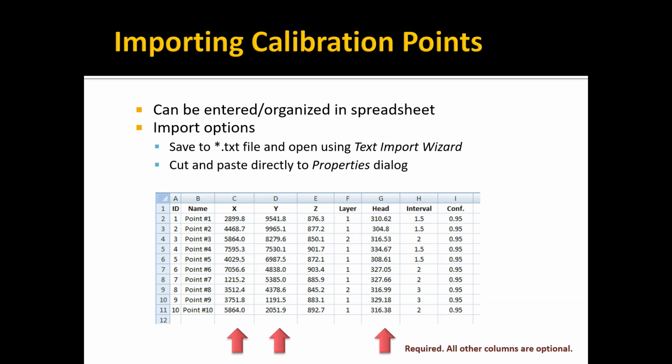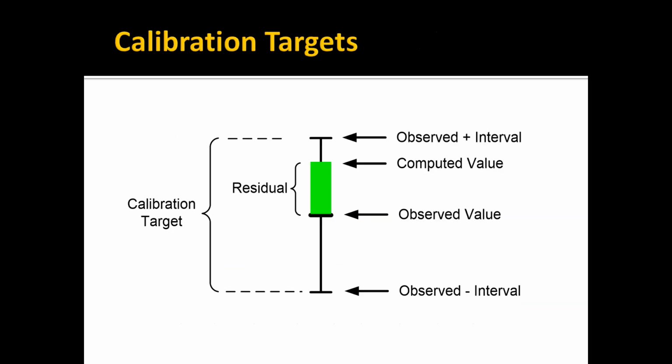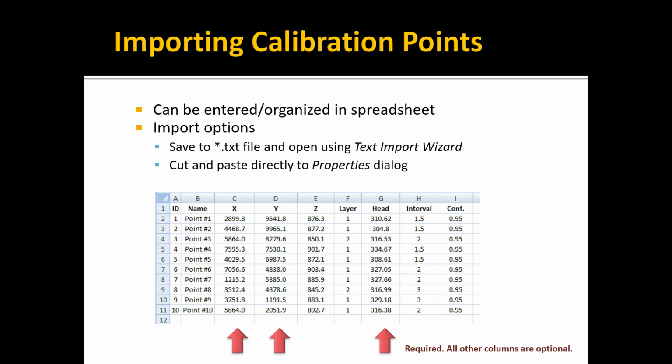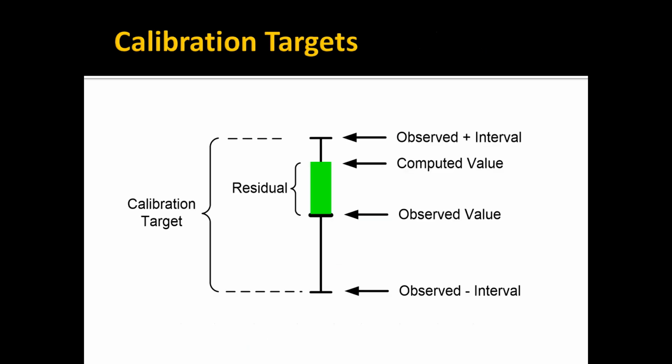This text import wizard, you just access it with the file open command. You do file open and select the file, and then there's the same kind of wizard we saw with the scatter point options. And you tell it what kind of file it is, an observation file, and then designate what each column represents. And we'll go through that when we do our exercise in class.